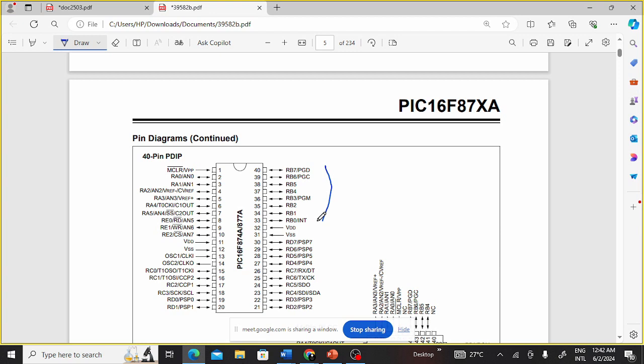So what do we call external interrupt? Interrupt, as we're going to be looking at it in detail in future. After GPIO pins in this class, the next thing we want to talk about is interrupt. So there are internal interrupts, there are external interrupts. So this is an external interrupt. This interrupt can be configured, maybe rising edge or falling edge.